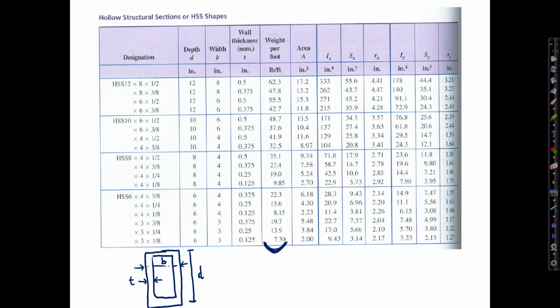In general, you want to choose the lightest section that you can, which will have the least amount of material. You could also look at the cross-sectional area. Weight and cross-sectional area should be proportional. In terms of design, we'll assume bending about the strong axis, which in this case, if the beam is taller than it is wide, the chart is assuming the x-axis to be outward and the y-axis pointing up.